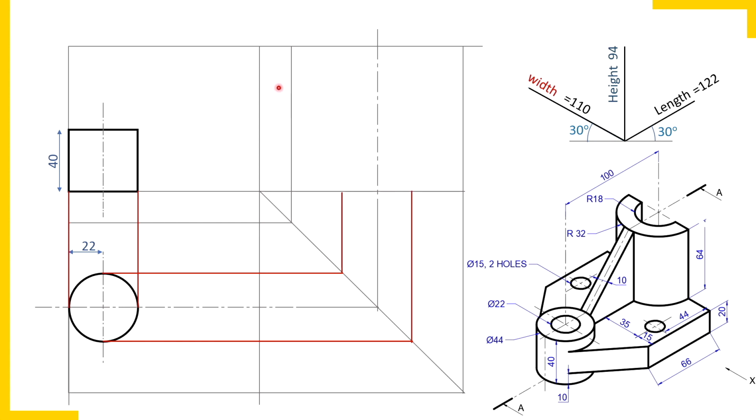Once again, when you draw three rectangular boxes, don't forget that the side view box is to be drawn by drawing end projectors only. You need not measure it independently. But remember, for smaller portions, it's your choice. For smaller portions, you may measure independently in each view.